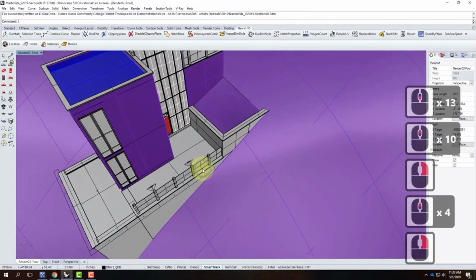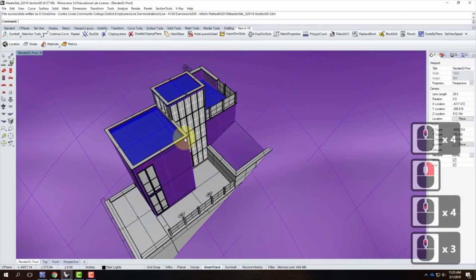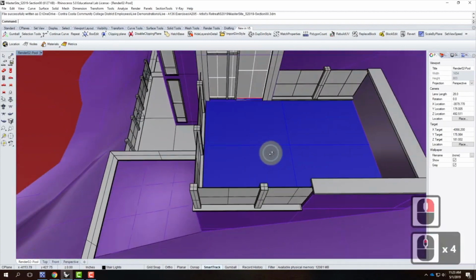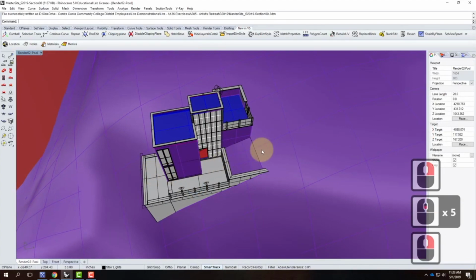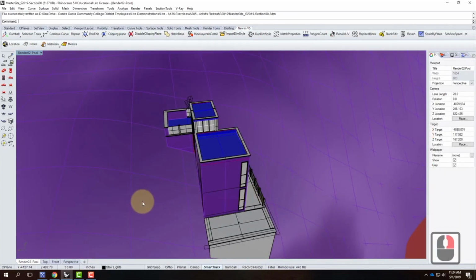And I have to think about, where do I want to cut the section through the building in the first place? Because that's certainly part of cutting the section. It's not going to do too much good to cut the section in the back here. Cutting the front off the building right through here, yeah, that might be valuable. Cutting this side off the building right there, that might be valuable. So you want to think about where you're cutting and also what you're looking at when you cut through. And so it's going to vary depending on your particular building.